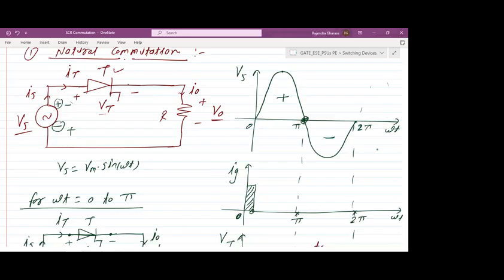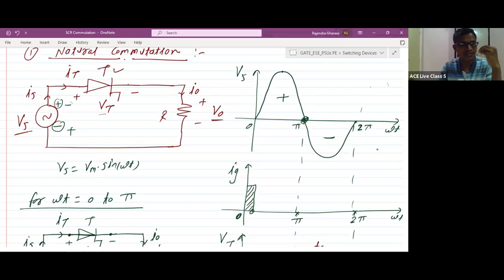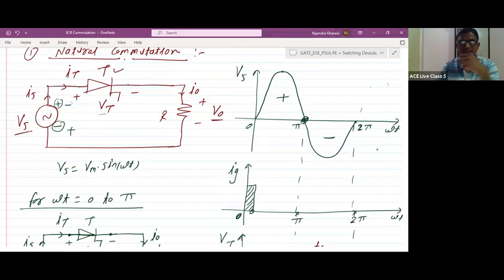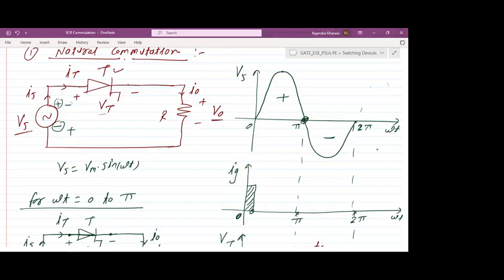The voltage commutation circuit is very complex, but we are using it for commutating, even in DC to DC converters and inverters. It is complicated, but it plays a very crucial role, because if your SCR fails to turn off, definitely your circuit output will change. So that's why we need to put that commutation circuitry there.